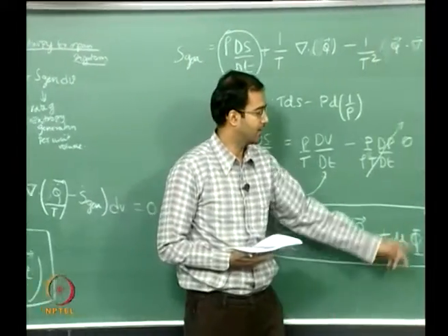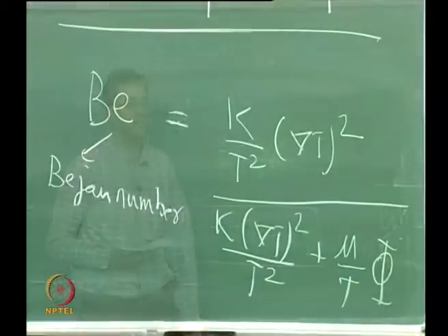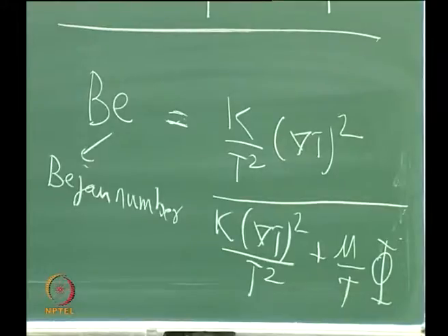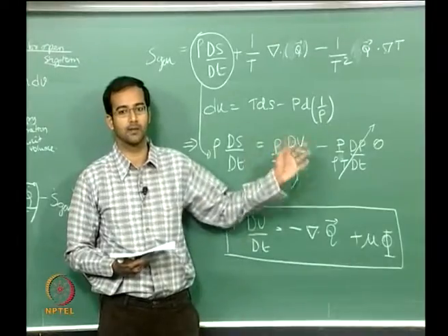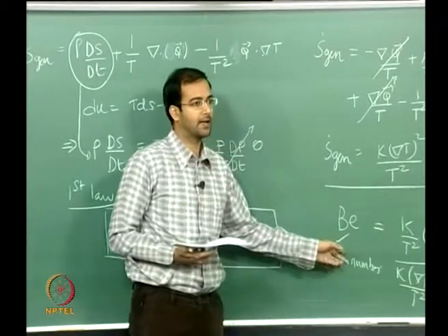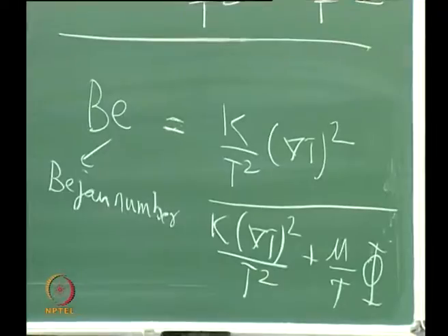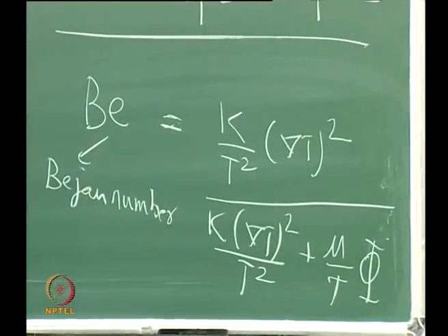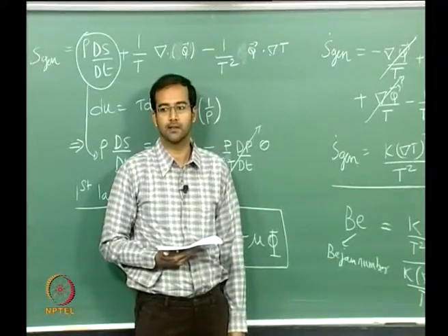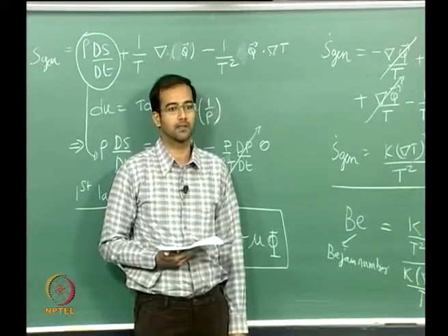Okay, and I think the Bejan number was basically given due to his contribution for this work particularly, and this measures if your Bejan number is some value, say about 2, it tells you that the majority of entropy generation is through conduction. Okay, and if it is much lesser than 2, it tells the majority of entropy generation is through viscous dissipation.